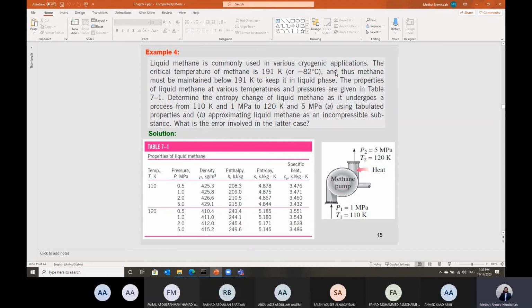In the gaseous form, we cannot provide the space for the gas, or if we don't have a significant amount of this gas, then we have to compress it to very high pressure. And this is expensive first of all, and it is dangerous as well to have an explosive gas under high pressure. So usually in different cryogenic applications in the liquid form, we liquefy the gas.